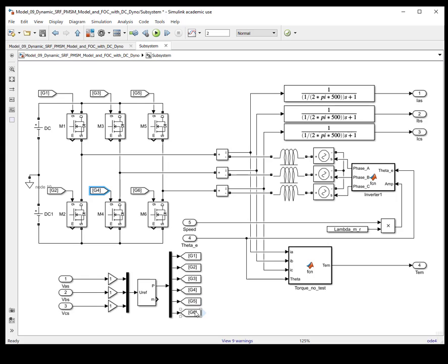So you're going to apply these go-to labels to the 6 signals, and then you're going to place them to each of these MOSFETs. So each leg, each phase, has 2 MOSFETs here, right? And these are the same MOSFETs that you have in your Simscape Power Systems blocks. You're going to have 6 switches, and you're going to apply these labels to each of them, and then you can have these connections going into each of the phases.